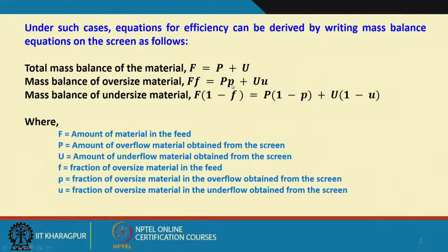So, that 0.8 is the small p, and you have got 60 tons of your u, that is your undersized material. So, the remaining 8 tons of coarser material have reported here. So, what is the fraction of that, 8 out of 60 tons? That we have to calculate, that is around 13%, or 13.5% to be precise. So, it will be 0.135. So, that is the small u.